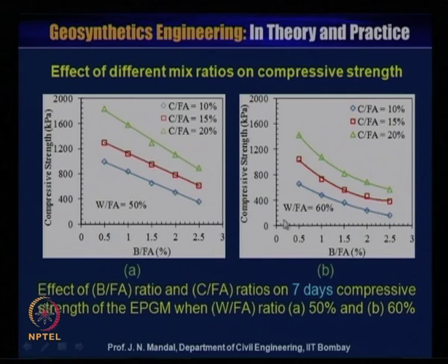But in the case of water to fly ash 60%, you can see this curve is not linear, as it is for 50%. It is a little bit non-linear, but overall the improvement has been observed when the water to fly ash ratio is taken as 50%, because the compressive strength is higher than when it is 60%.